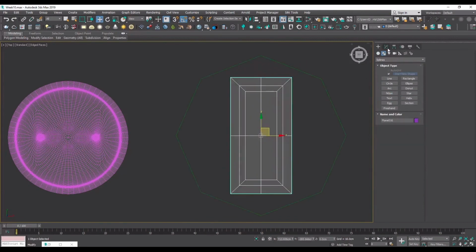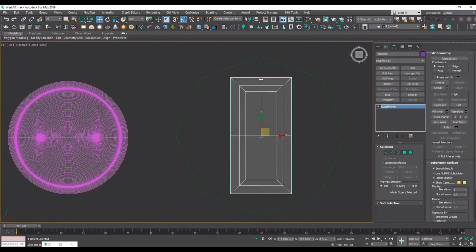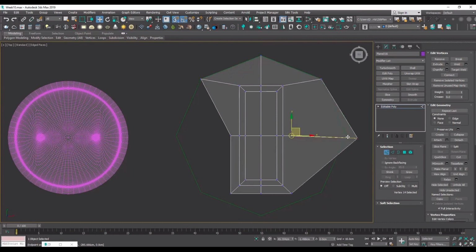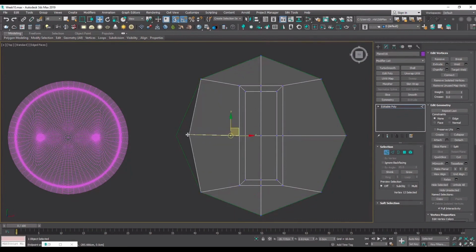So why did I repeat my operation? That's because I'm going to actually use the vertices and make our circle shape out of them. Just as you see, I'm moving and matching the vertices and snapping them to our n-gon as a reference. By using this way, I'm not going to be concerned with the base shape of our mesh anymore.